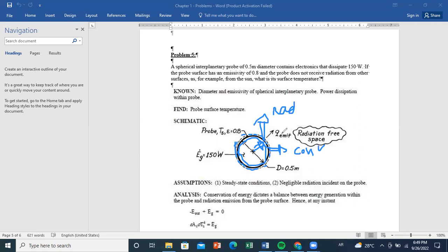So through this thin layer, the generated energy will be transmitted by conduction in the material. If we do a small analysis, we can say the following. The generated rate of energy will be transferred throughout our system through conductive effects, so it's equal to Q conduction. And this conductive flux will be transferred to the outer environment through radiation and convection.